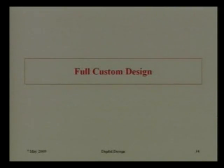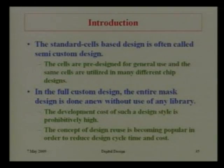Okay, this is mainly semi-custom, which is what we have discussed, that is needed for digital design. For digital design, this semi-custom approach is possible. That means a library of AND, OR, NOT, NAND gates with their delay, that for a particular W/L ratio, what will be the delay with all characteristics, as if the library is available, and that library must match with my fab lab, what I will actually be doing in my fabrication lab. So using that I am synthesizing my circuit. That is the summary.